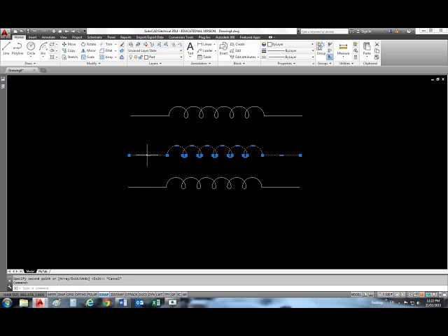So let's take this and use the rotate command from this end, and now where do I want to rotate it? I will type 60 degrees because I need to go counterclockwise, which is positive. Enter, and then move command. Move this, spacebar, from this end to that end.